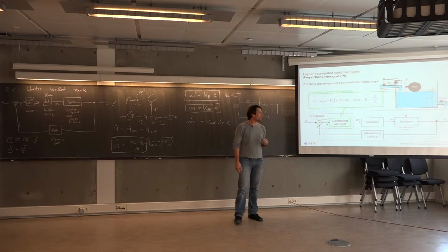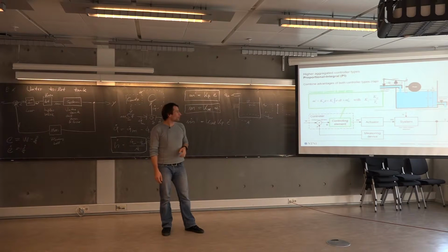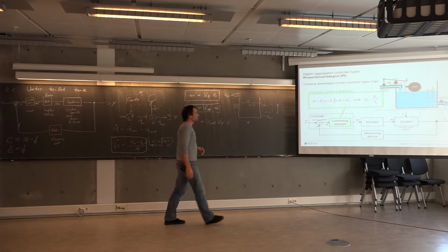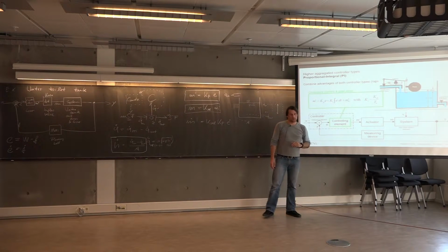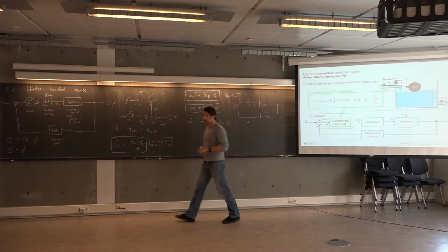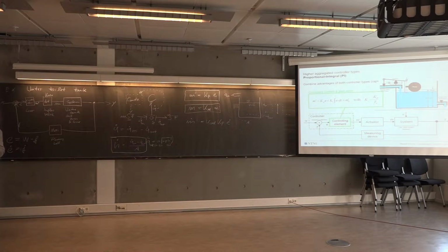But the controller would react to that change, and you would actually be able to completely level out or get rid of this error by doing so. And this is nothing else but an integral controller action, which one could implement in this system additionally. Probably wouldn't make much sense for a water toilet tank, but nevertheless.